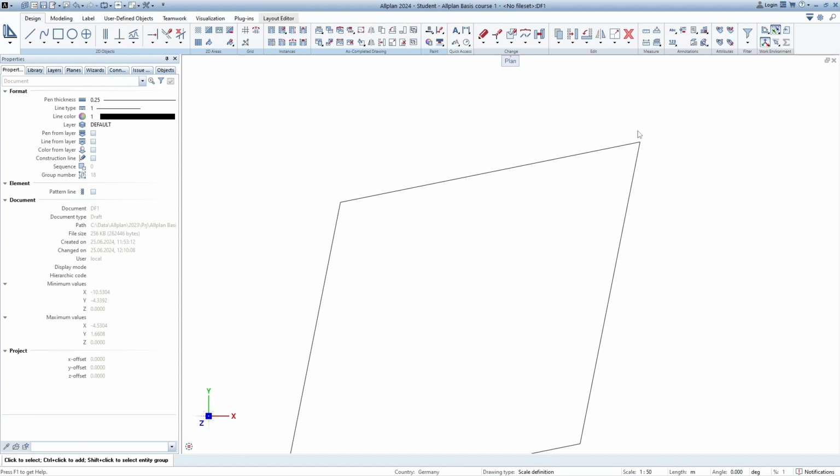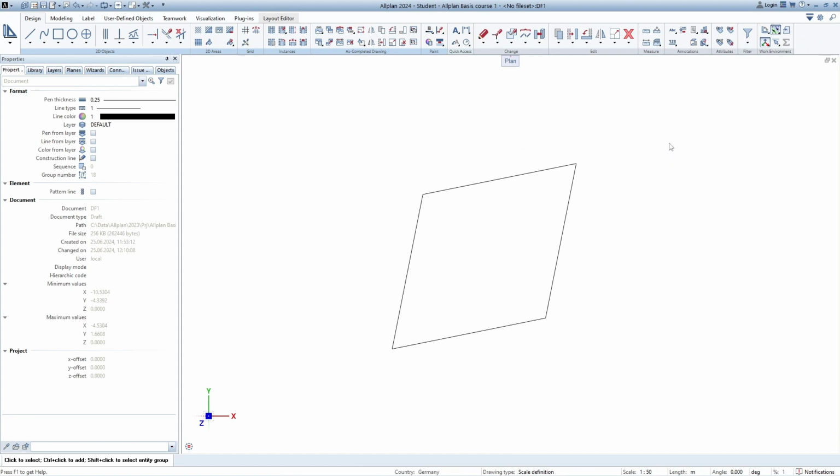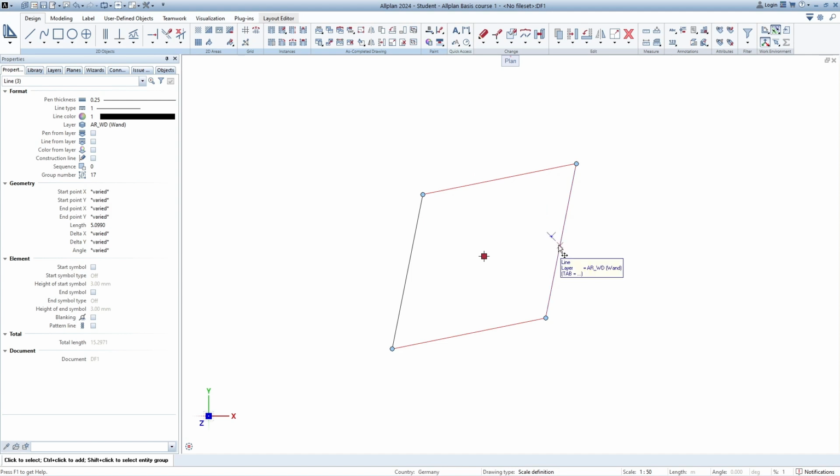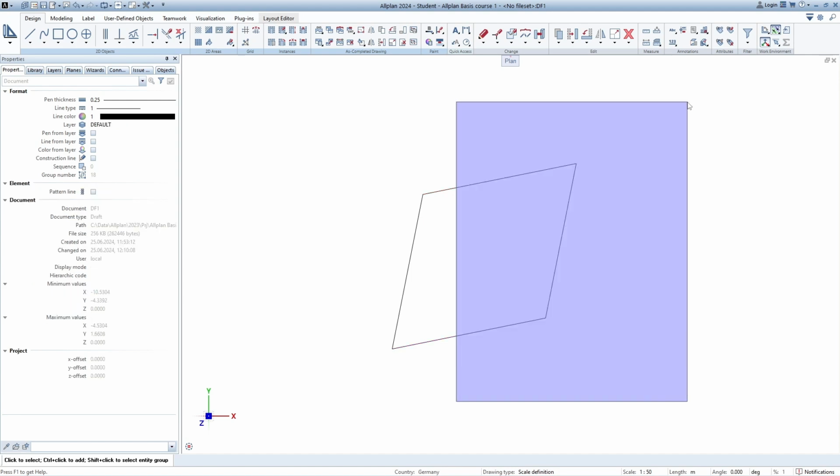And the thing here is, if I go from the right to the left, I have the green field. So what basically happens with these kinds of lines, I have the upper line, the right line, and the bottom line. As soon as I release the left mouse button, all these lines will be activated because the top, the bottom, and right are intersected or fully intersected by this field. So you can see this one became red, this one became red, this one became red. Let's go ahead and do the opposite.